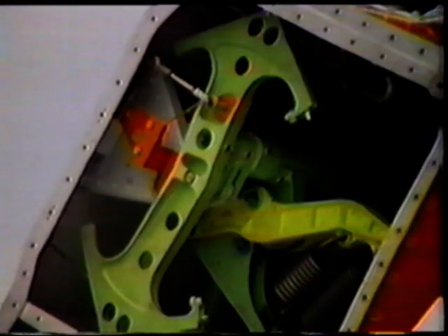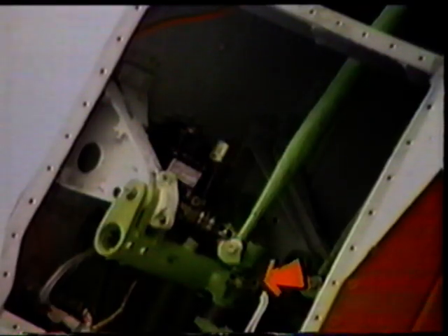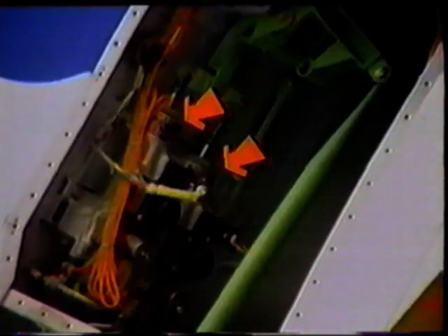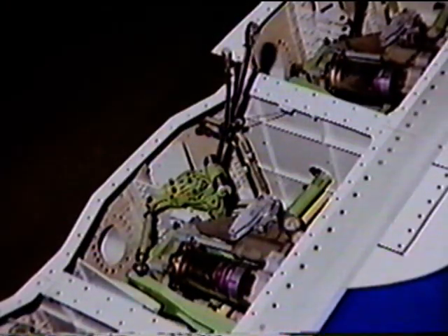Located above the autopilot servos are the aft quadrant, field centering and trim mechanism, rudder trim actuator, rudder ratio changer actuator, rudder ratio changer mechanism, load limiter, two yaw damper servos, centering and bias spring, rudder position transmitter, and three power control actuators which are powered by independent hydraulic sources.